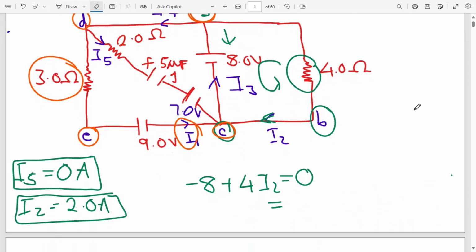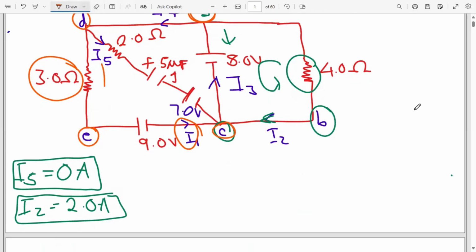You can tell the direction of the loop that I've given is anti-clockwise as usual. And the current I1 is also directed in this same direction. So this is I1. The voltage across this particular resistor is along the direction of current. That means we're going to have a voltage drop at this point. So I'm going to have minus 3I1, because the voltage across this resistor is in the same direction as the current.